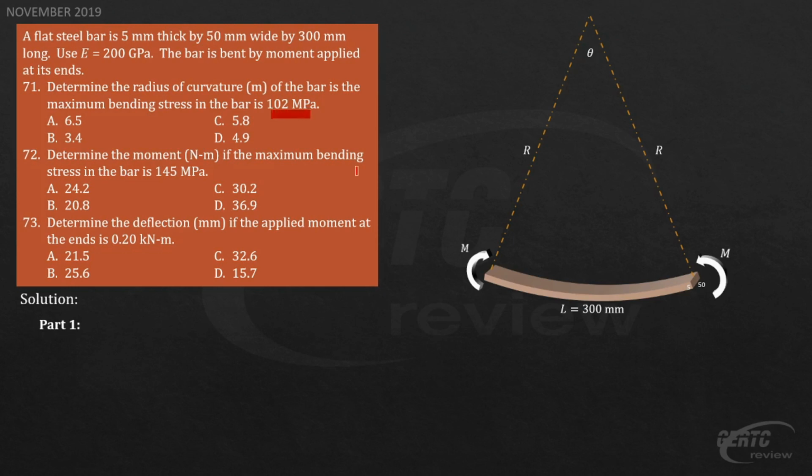So there is a formula for this. So again, meron akong sa lecture sa review, didiscuss ko to, diderive ko pa nga to. Hanapin nyo under stresses in beams. Meron doon, may derivation ako doon. So R is equal to E times C divided by FB max. E times C. Diderive ko to. Tingnan nyo doon. Hanapin nyo lang sa playlist. Nandoon ito sa playlist.